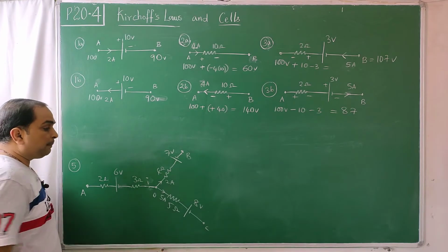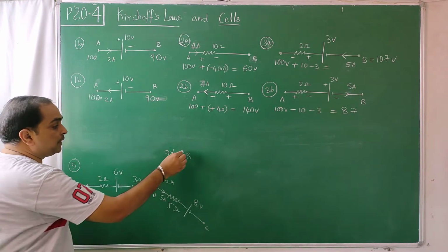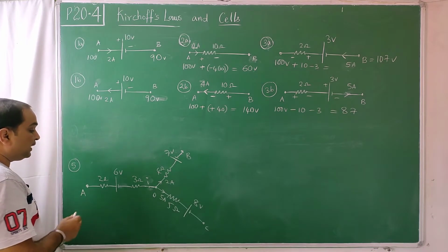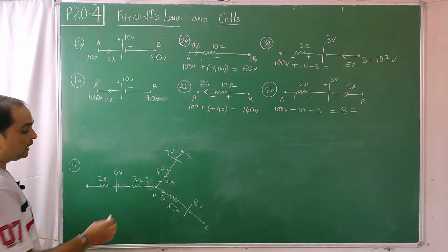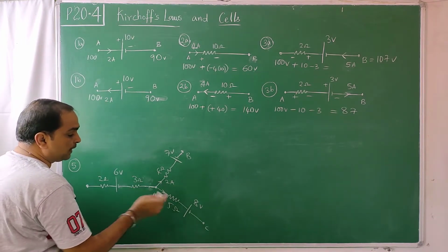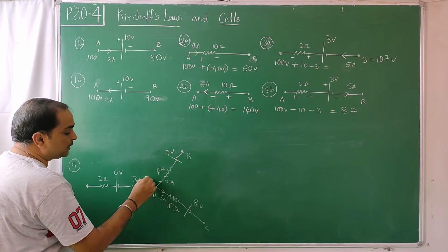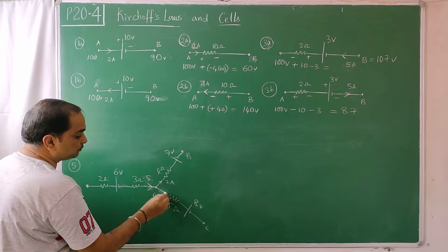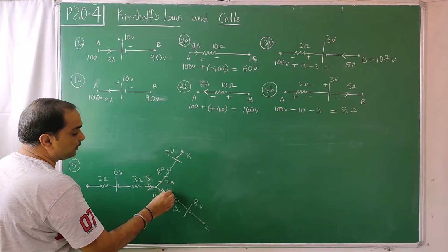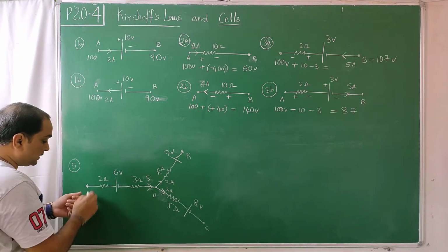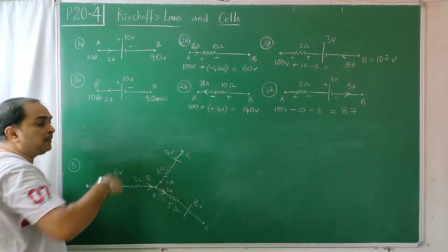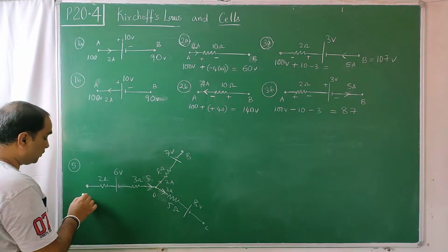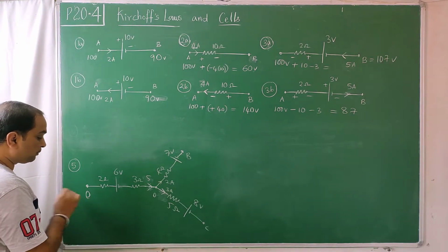So accordingly, first I should find the potential difference between the different terminals, assigning one potential, say 0, at some place. Instead of this I will take here the current I, and this I will remove. See, this is 5, this is 2. So this is say 3 amperes. We hope that there is some other terminal connection which decides the potentials of these points. Then we can take. So suppose this is at 0 volts.